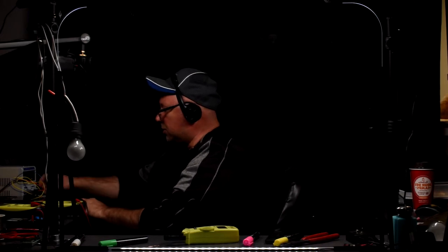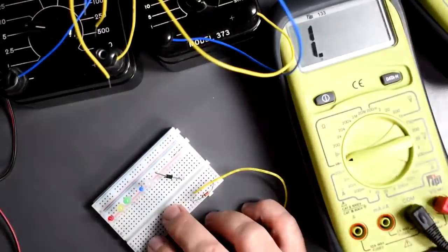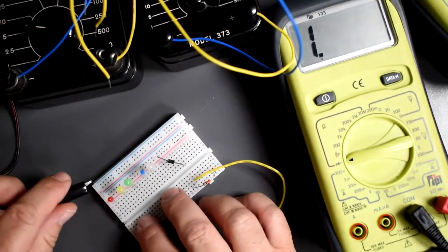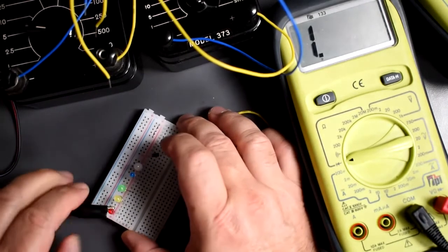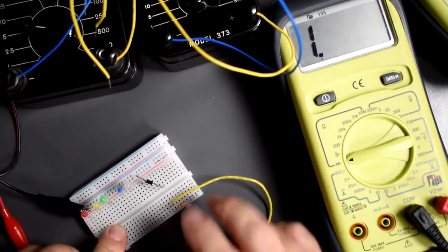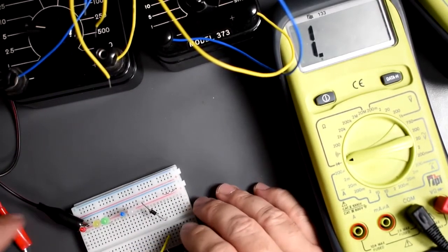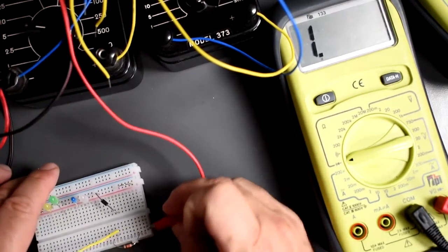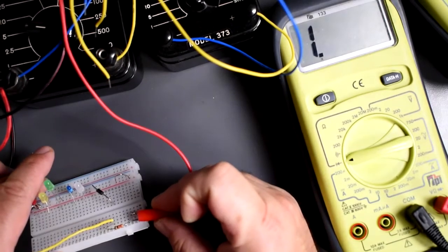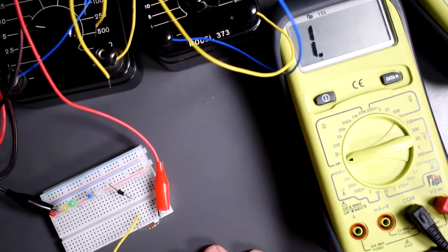And the way we're going to energize this circuit is we're going to apply 5 volts. Here's our power supply, 5 volts. And this negative part is going to go to the cathode, and all the cathodes are connected together. And then we're going to connect the positive side to the resistor because we want to limit the current. If we just connect the power supply straight to the diode, we're going to burn the diode.